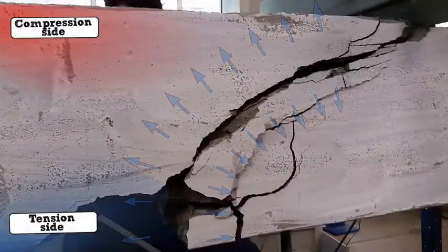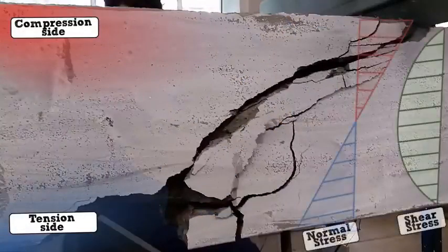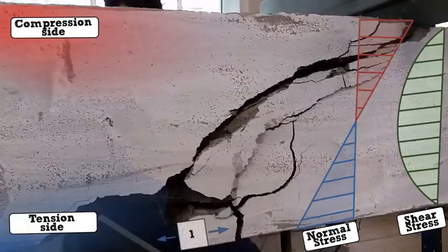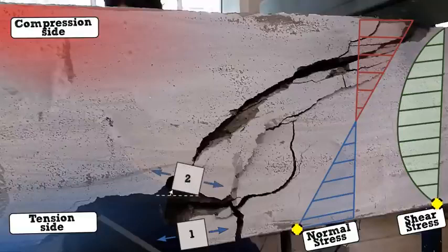At the bottom of the beam, there are no shear stresses, and therefore the principal direction, also known as the direction of highest normal stresses, is already aligned along the length of the beam, which explains why the cracks start out vertical at the bottom of the beam. However, as the crack propagates towards the inner part of the beam, the shear stresses experienced by the material are non-zero, which means that this is no longer the direction with the highest normal stresses.